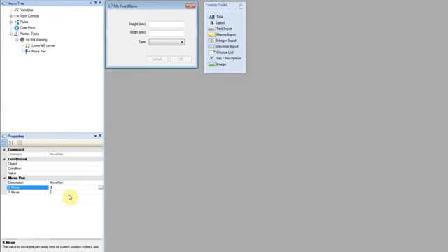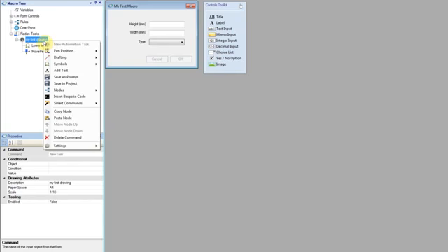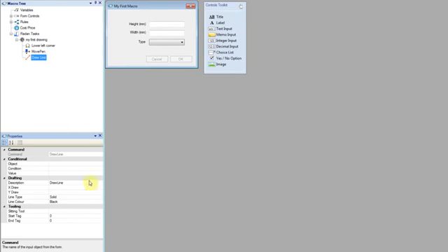Next we want to draw a line in the X direction by a length of the result of the width question. Select the automation node, right-click, select Drafting, Draw Line. Again take a look at its properties. Change the description to bottom line.